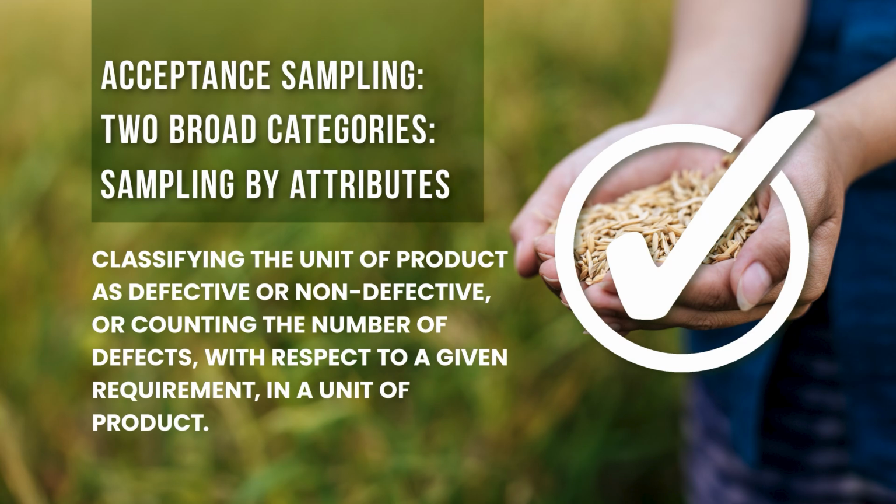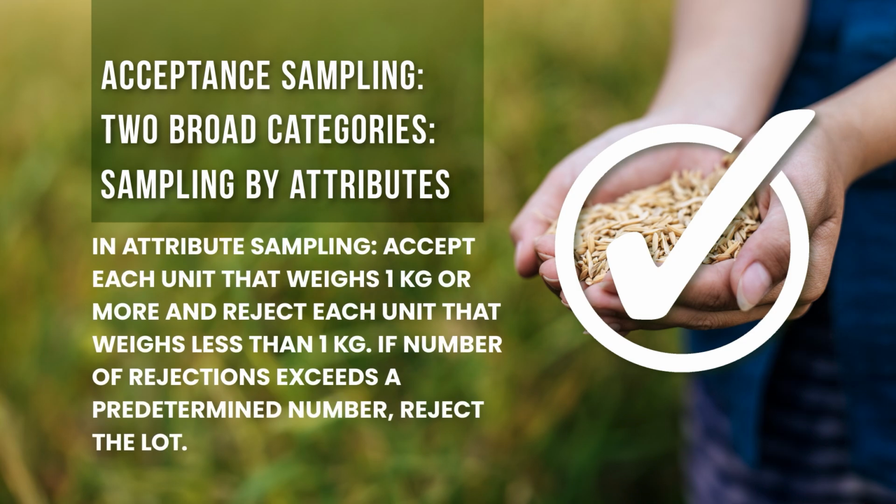A product sold in lots of 1000 kg, as I have told you, if you have drawn 1000 items, 50 samples and 2 samples are broken, then the whole lot will be rejected. So basically this attribute sampling is binary. Binary means it is very rigid, either pass or fail. So either an attribute is present in the test or not, that is to be checked.